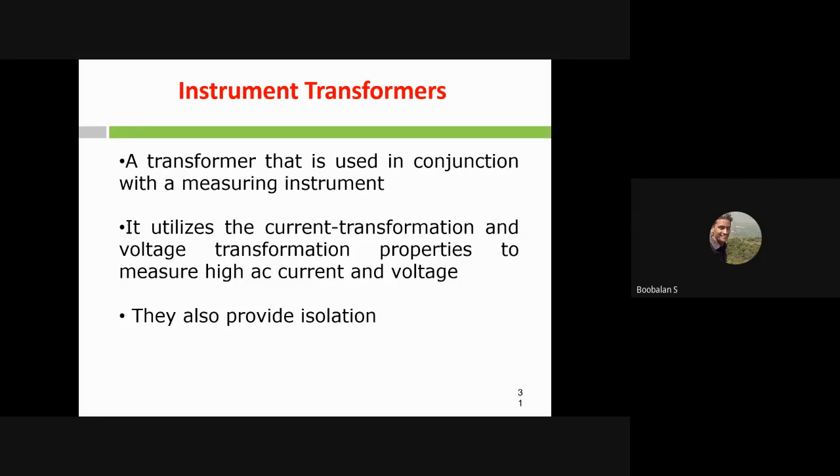So for metering purposes, after metering, the metering output is now connected with my CTPT, based upon my metering data, right? So this CTPT is going to give the data to my metering system. Based upon this CTPT value, the relay is going to be tripped, or the relay is going to be switched on or switched off for that particular device, right?